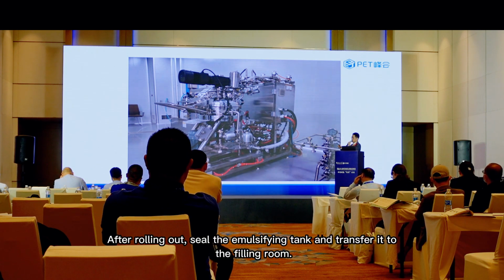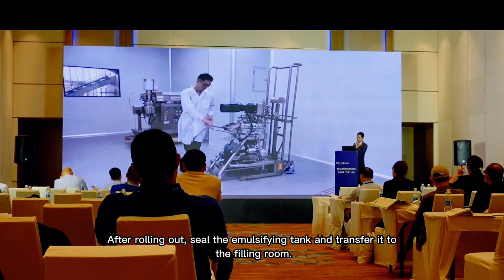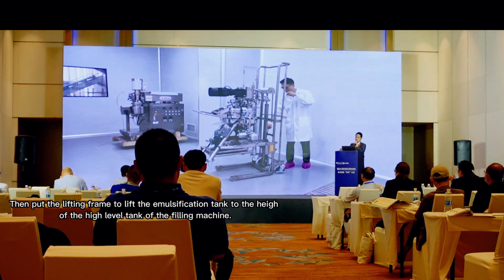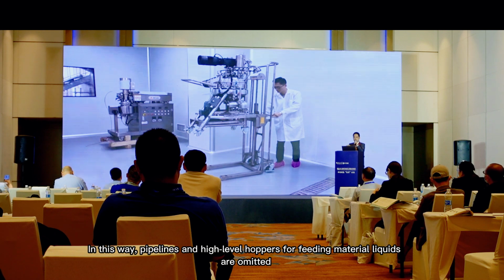After rolling out, seal the emulsifying tank and transfer it to the filling room. Then put the lifting frame to lift the emulsification tank to the high-level tank of the filling machine. And then connect the pipeline of the filling machine, and the emulsifying tank replaces the high-level tank. In this way, pipelines and high-level hoppers for feeding material liquids are omitted.